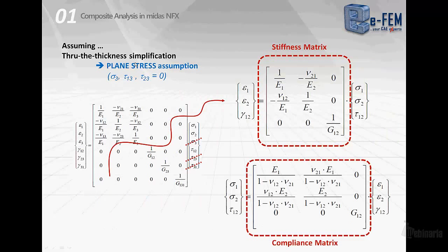If we assume that we can simplify the behavior of the material as a plane stress behavior, and this is not so big an assumption if we consider that the single laminas are commonly very thin, we can use this through-the-thickness simplification.